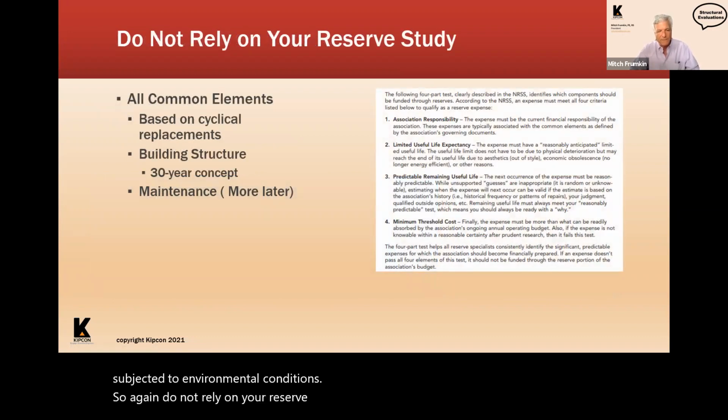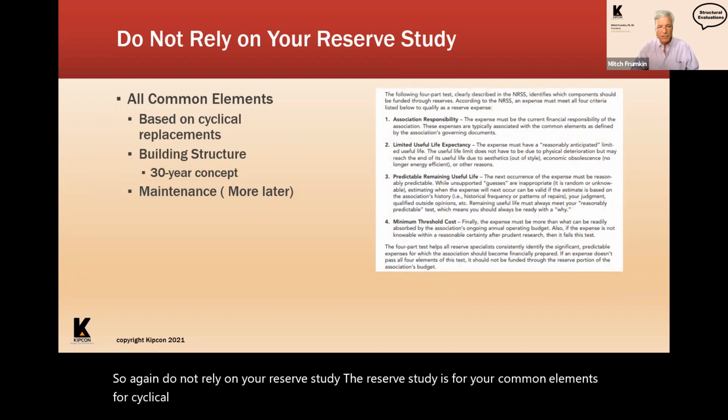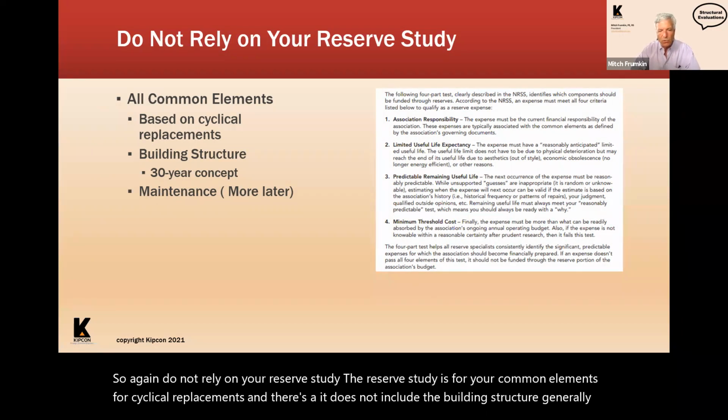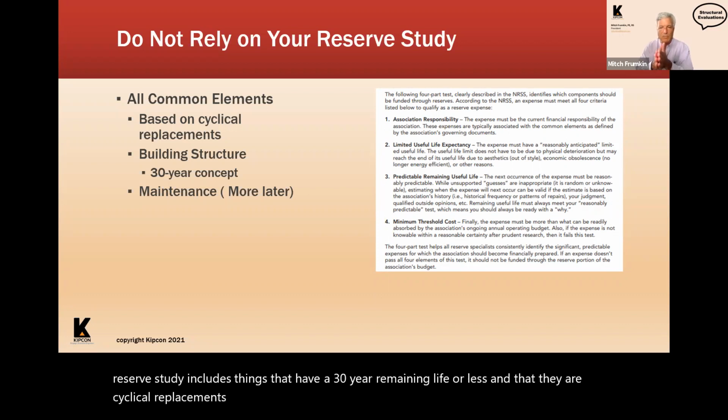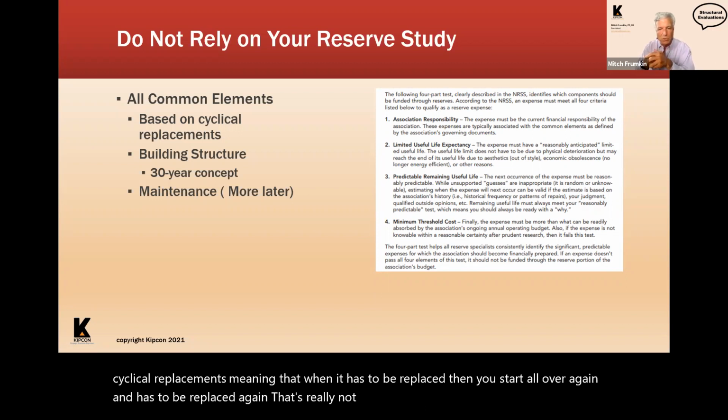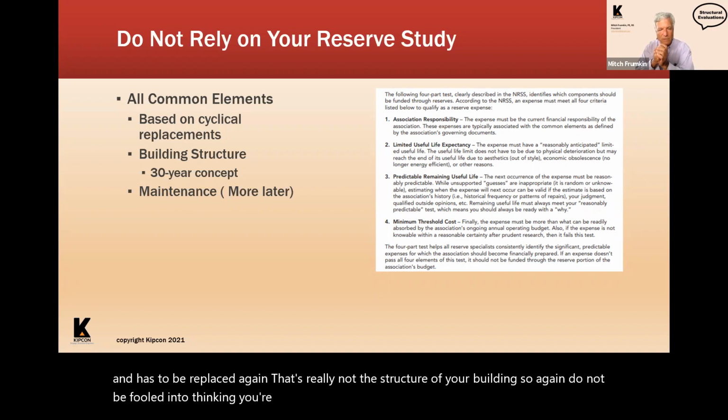The reserve study is for your common elements for cyclical replacements. And it does not include the building structure. Generally, the reserve study includes things that have a 30-year remaining life or less, and that they are cyclical replacements, meaning that when it has to be replaced, then you start all over again and it has to be replaced again. That's really not the structure of your building. So again, do not be fooled into thinking you're okay if you have a reserve study.